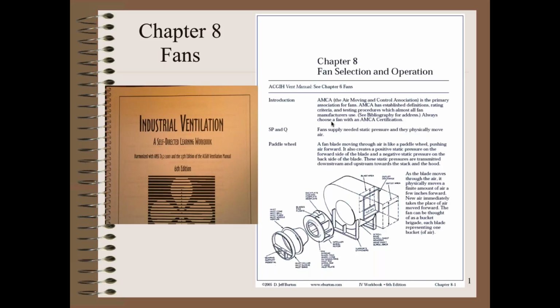Two reasons we might want to do that: because we can't discharge the contaminant outside legally or something like that, or morally, but usually I'm not too worried about morally, more legally. Or it's some sort of material that could damage the equipment. For instance, if it's an acid gas, it could corrode the fan. If it's an abrasive material, it could corrode the fan blades. So very frequently there'll be some sort of filter or removal device before the fan, and then some more ductwork, and then the fan takes over the brunt of actually causing the air to move.